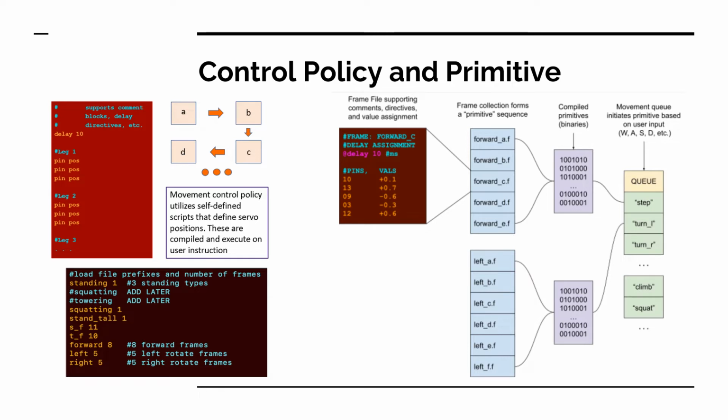And what we ended up going with was an entirely novel solution, implementing something called a movement queue. And the movement queue is, I guess, the highest level construct that exists within our code, because it is comprised of a number of different primitives, the primitives themselves comprised of different frames, as alluded to in previous slides. Now, this is really significant because this basically takes very primitive movement patterns and makes them discrete, which is useful when you're running this bot, not only because it makes memory very sparse, but also because it makes memory very reliable.